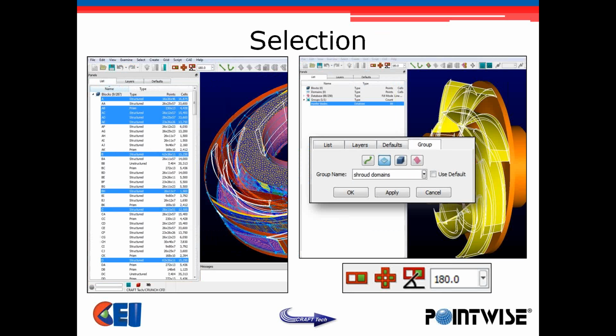Selection also becomes extremely important, when you can have hundreds, if not thousands, of entities living in the display at any given time. How do you go about selecting them? We've talked about the mask panel before and picking entities in the display window. The mask panel allows you to do very targeted entity-based selection, but you can also do selection from the list panel just outside the display window. Maybe you've named certain entities and you could do a drop down on that entity list. In this case, we're picking blocks by a given name and they're being selected in the display window and we can operate on them. Another thing you can do is create groups.